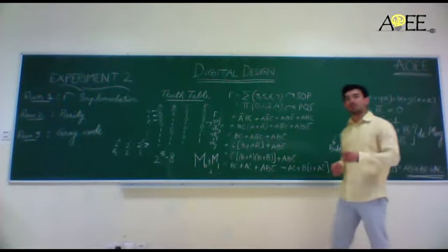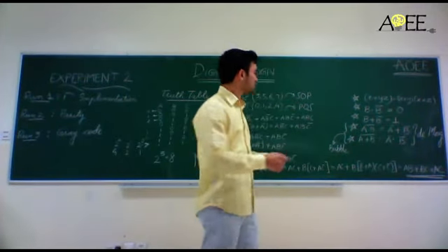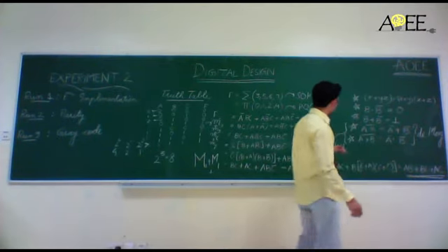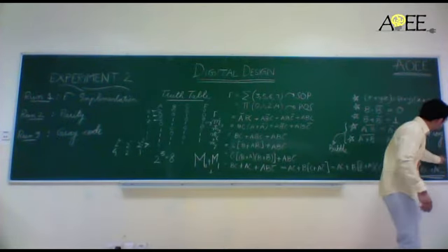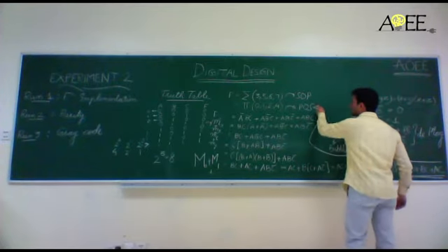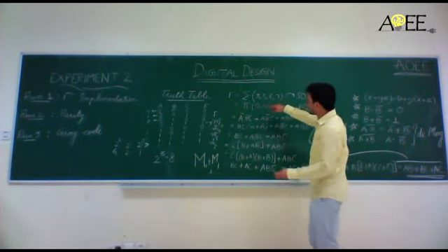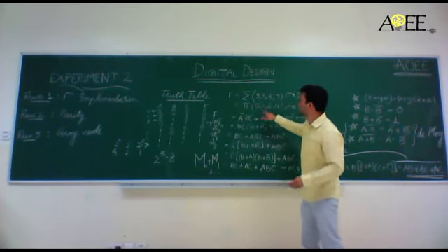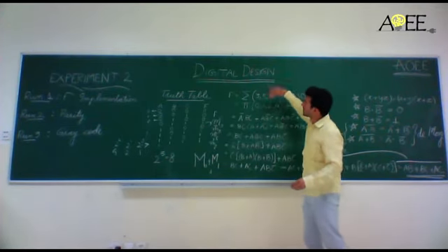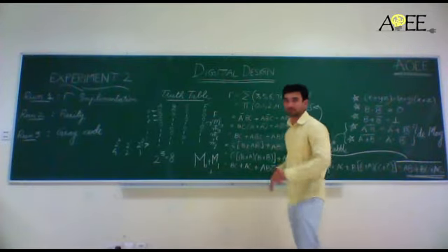Note that sum of product and product of sum forms are inverse of each other. So, if we have the sum of product form in simplified manner, then taking the complement of it and simplifying it will give the product of sum form. So, that has to be done. As you can see, the numbers include 0 to 7, right? Some of the numbers will be in the SOP form, and the other remaining ones will be in the POS form. That's how it is done.